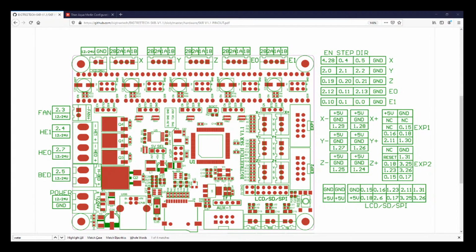Let me point to where you can see me pointing. So right here it says ground. Right here it says voltage. If you go over here, these equate to voltage instead of ground. And then over here, this was the reset button, so it might be ground. So now you can see why I'm confused, because over here, ground is actually the signal pin, and then voltage is actually the circle. So they're using these indiscriminately, which is kind of bad practice.